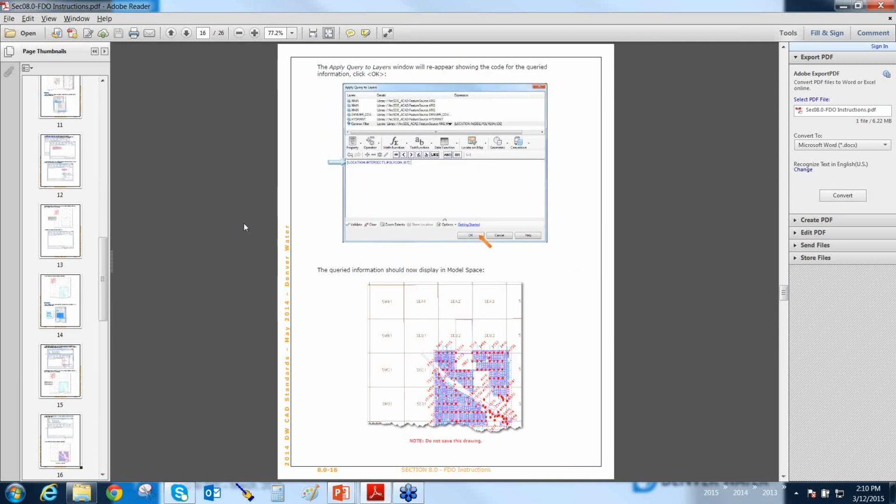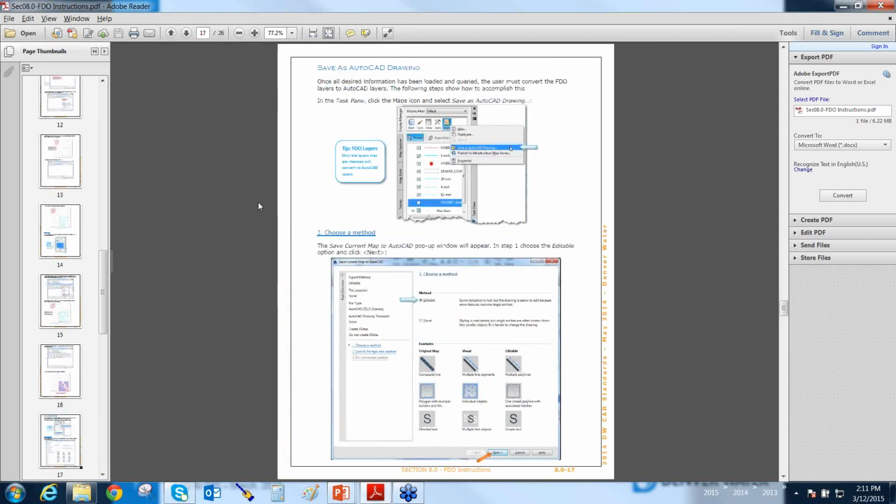Yeah, this particular document is actually pulling our GIS data back into CAD. This is kind of the end of the circle, if you will, where our CAD users want to use the information that they know is accurate within our GIS system. So this is how they utilize it, and this is how they pull it in. You can't just use map features. This particular document goes all the way in from pulling the GIS data into Map 3D as live data, and then going through the whole process of saving it as a drawing so that you can actually use the features that were map features before that are now dumb AutoCAD features, if you will.